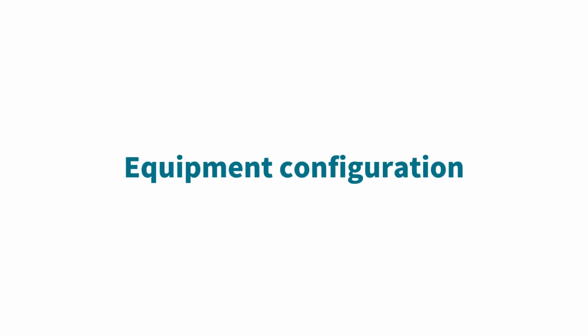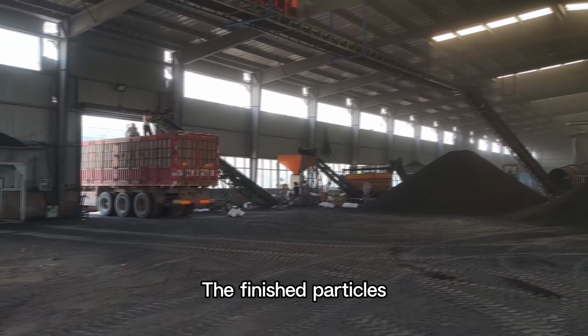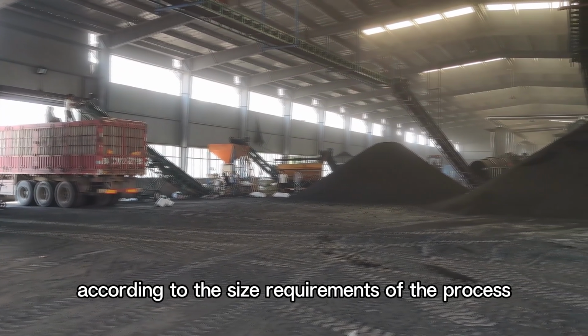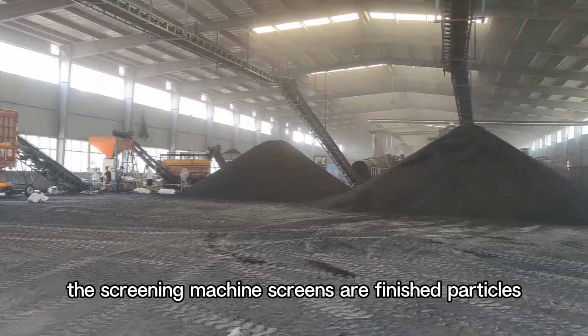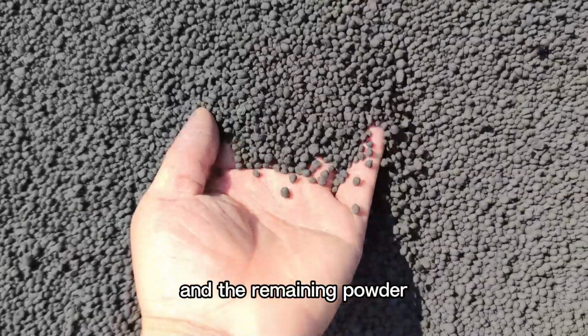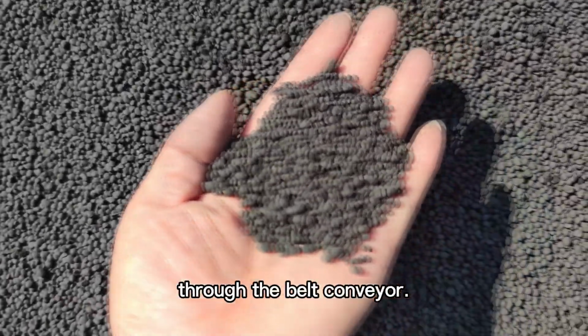Screening section. Equipment configuration. Drum type screener. The finished particles are sent to the drum type screening machine, and the finished particles are screened out according to the size requirements of the process. The screening machine screens out finished particles, powders, and large particles. The finished particles enter the coating section, and the remaining powder and large particles are returned to the grinding section through the belt conveyor.